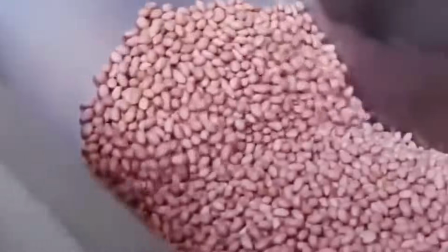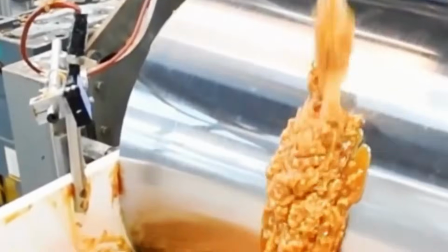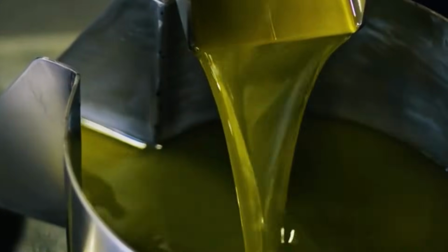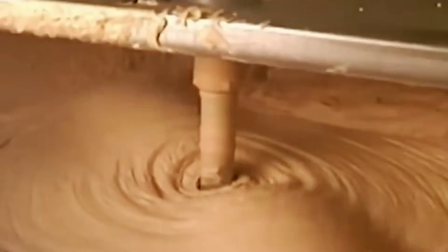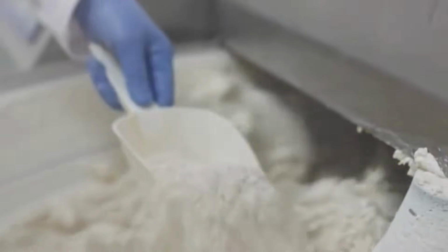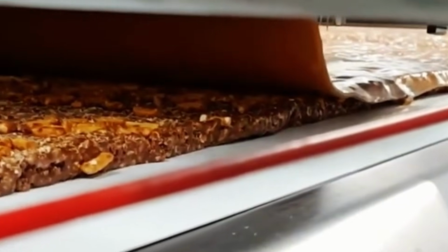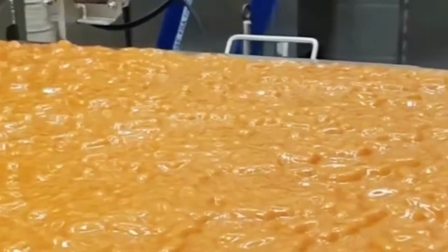Each blade is aligned using digital edge sensors to maintain cutting accuracy within plus or minus 0.5 millimeters. The individual lanes are separated using diverging conveyors and conveyed into the guillotine cutter, where servo-driven blades slice the moving slab into individual bar lengths, typically 38 to 52 grams per unit. Cut bars are spaced automatically using smart belts that adjust speed based on line accumulation to prevent product overlap and damage. Any misshaped or undersized bars are rejected using pneumatic knockoff arms.